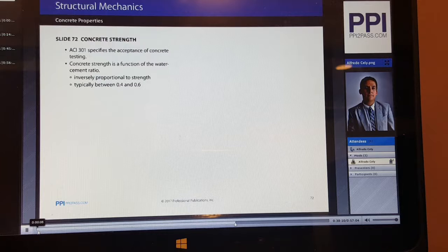Cylinder sizes of either 4 inch by 8 inches or 6 inch by 12 inches are permitted, which are the ones used to collect the samples of concrete. Smaller cylinders are used when the compression machine has a lower capacity. Single strength tests could be performed at times other than 28 days, but the tests are specified as 28-day tests.